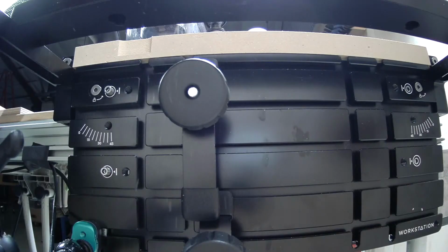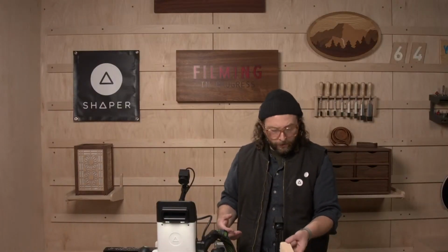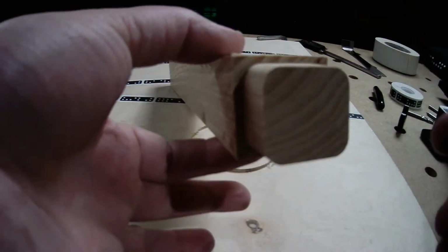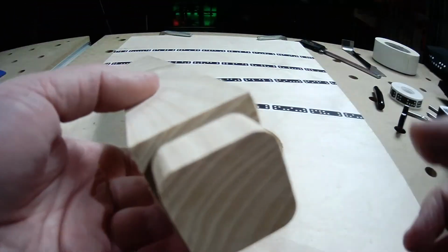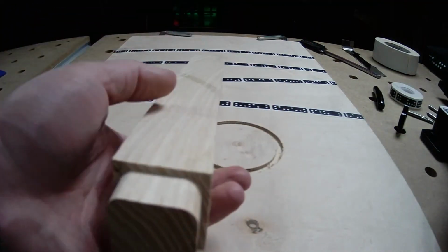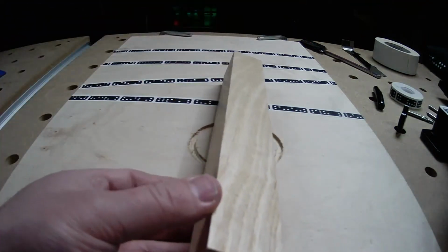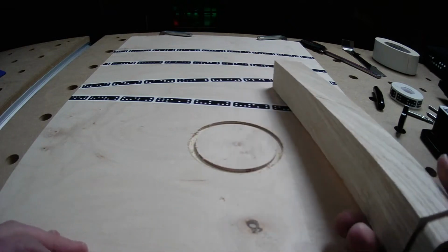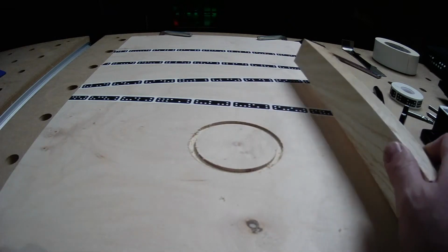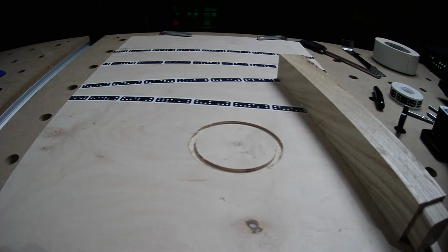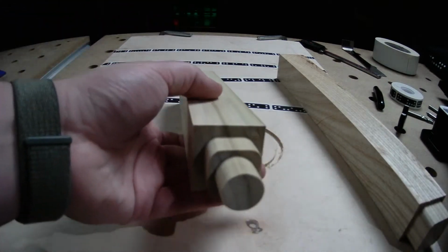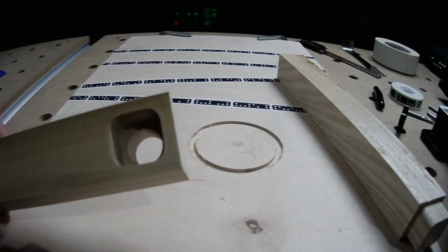The bottom of the support bar is an end stop, and the 2 alignment pins here. As long as I do those 3 points again, and make sure that it's really snug against those and clamped well, I can take a little bit off of this and get the exact fit that I'm looking for. And you guys saw that's completely on tool. So there's lots of furniture that can be made, and it doesn't have to be just squares. Like we have this other tenon and mortise set up over here.